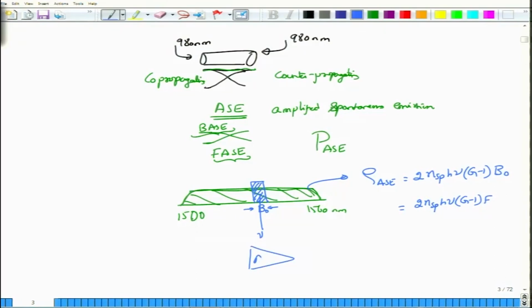If you look at any amplifier, you might have some input signal to noise ratio at the input side, and then a signal to noise ratio at the output side. Usually it turns out that because amplifiers add their own noise, the signal to noise ratio worsens, and how much it worsens is given by the noise figure or the noise factor. This is the further degradation that you would expect, because most amplifiers are not ideal amplifiers and they induce noise and have this noise figure. It turns out that the noise figure is actually a very fundamental property.